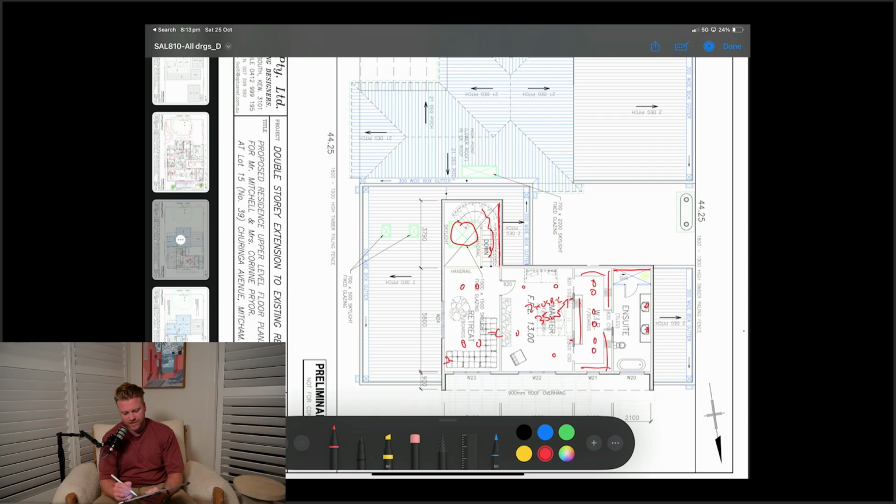Again, two downlights over the sink, some over the bath. We're not lighting this area. Probably put a nib wall, I reckon, somewhere there. And what we'll do is a low-lying wall light next to the toilet as a bit of a night light. So this is where we have our sensor